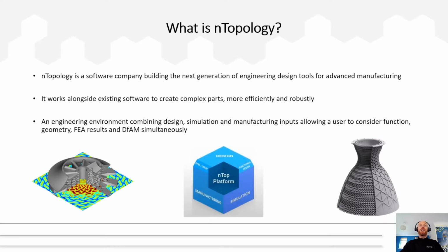So rather than a CAD package, we can think of Platform as an engineering environment where you can combine design, simulation, and manufacturing inputs, allowing a user to consider function, geometry, FEA results, and DFAM all simultaneously. So unlike traditional CAD packages, where we simply create a 3D model, in nTopology we create a process built on the foundations of maths and data. This means that if we create a process to build a heat exchanger or a rocket nozzle, we never have to design another one. We only have to adjust parameters to account for a revised space envelope, for example, and the workflow will automatically generate the new design.